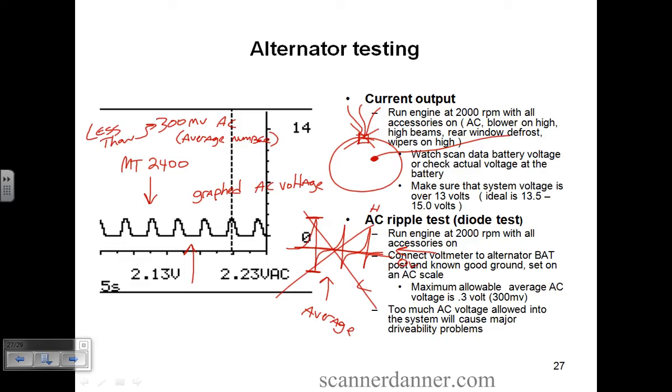This is as simple as it gets if you think about it. Now, the key though would be, can you get to the connector? Right? But if you suspect an alternator is giving your vehicle a problem, that's what you can do. Disable it, run the car off the battery for your quick test drive and see how it runs. Ran beautiful with the alternator unplugged.